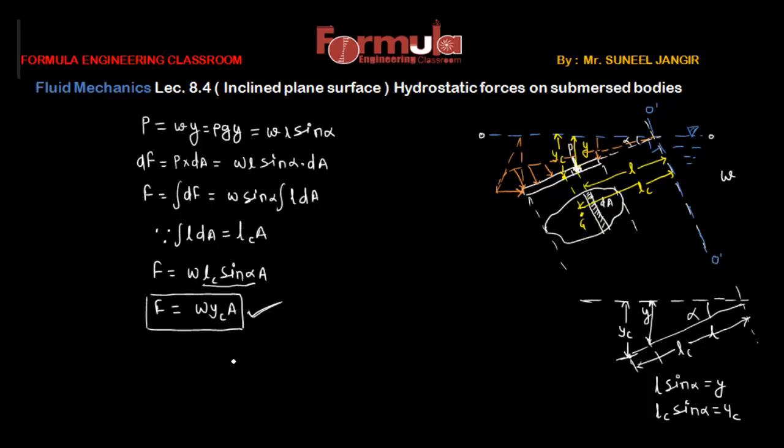Now let's understand the concept of center of pressure, that is the point of action of this hydrostatic force W Y_C A. Again we will calculate the center of pressure by using the principle of moments. First we solve the moment about an axis that we are considering, O dash O dash, that is the moment applied by the elementary forces about this imaginary axis.